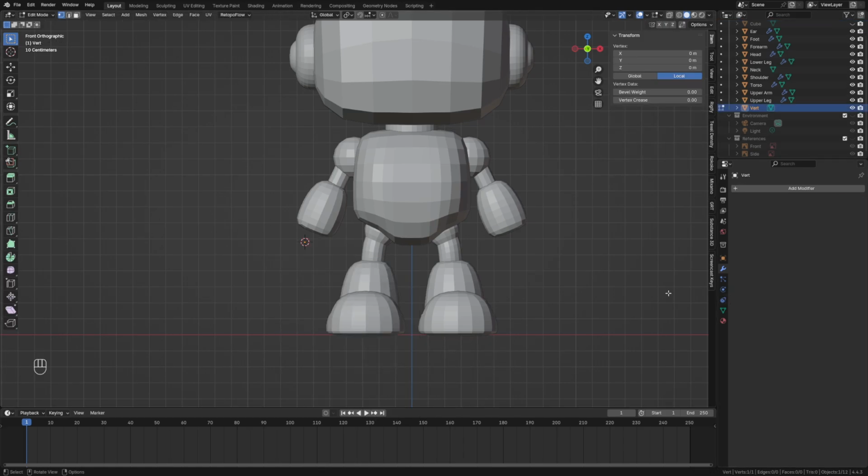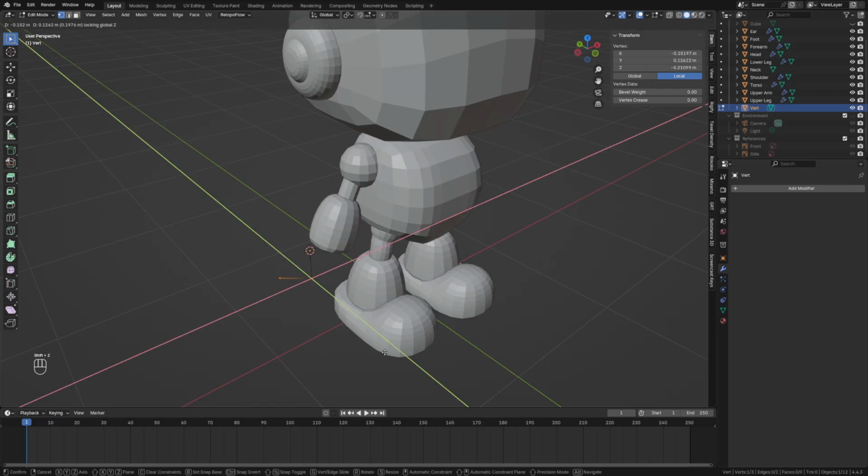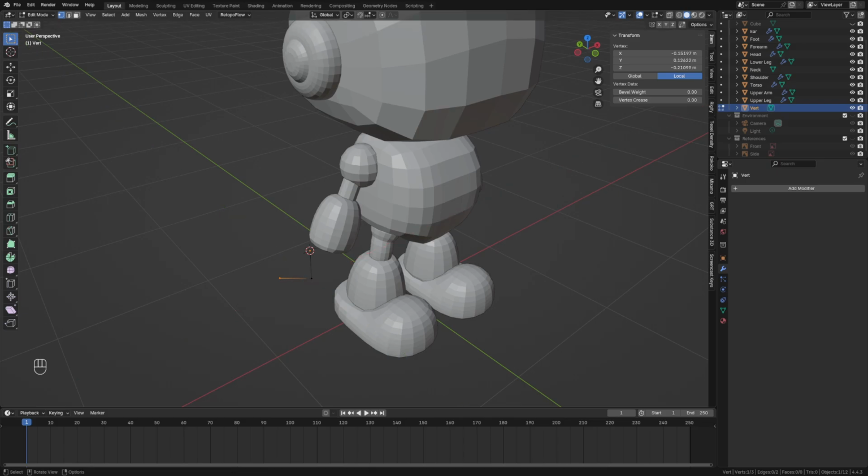When we created it, Blender automatically switched it to Edit Mode. And this vertex is selected, so I can extrude it now with the E key. When extruding, you can press Z to constrain movement to the Z-axis. I will extrude again, and this time I will press Shift Z. This lets you move freely along X and Y while keeping Z locked. I want to create 3 fingers, so I will repeat this extrusion 2 more times.